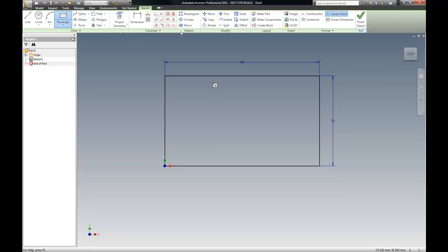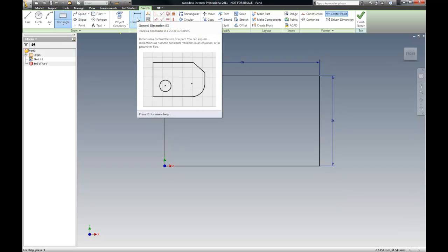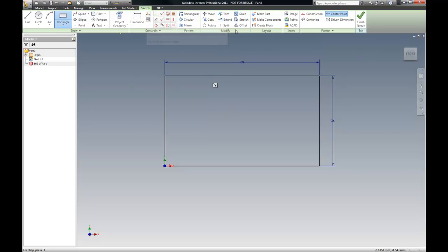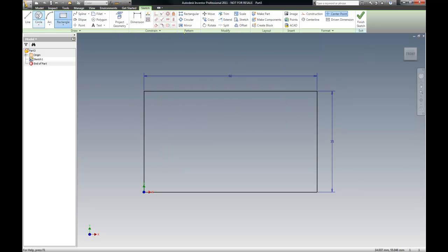Now let's see if we can do some interesting stuff here. I'm trying to see what kind of angle they give us, if they do at all. They're not giving us an angle, so we're going to do our circle first, and we'll build this slowly. Notice it picks the midpoint. I can do my direct input. It's going to be a radius of 10, which would be a diameter of 20. I'm going to hit escape a couple times.